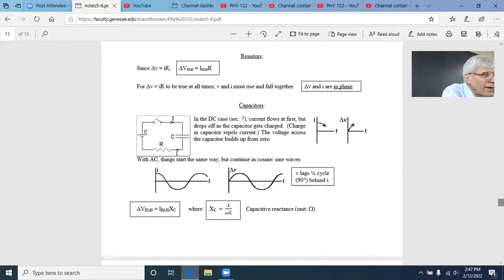Well, if you look at that for maybe just a millionth of a second, there isn't any time for it to change any meaningful amount. So if you're looking at what's going on effectively at an instant, you're talking about direct current, even in an AC circuit. So Ohm's law says that the instantaneous voltage equals the instantaneous current times the resistance.